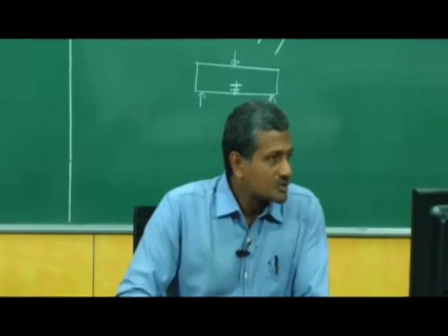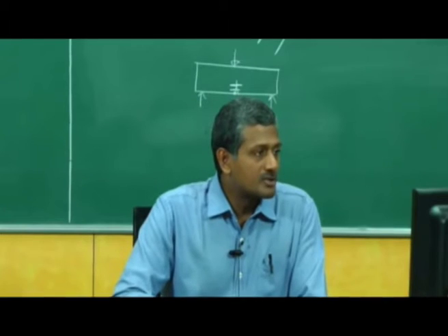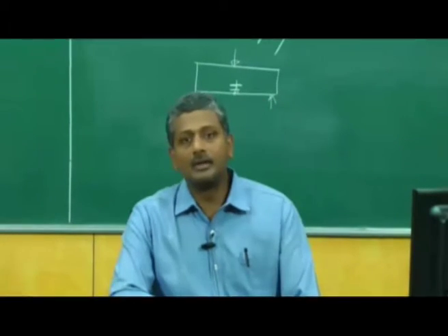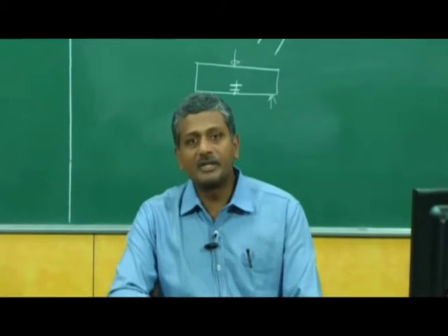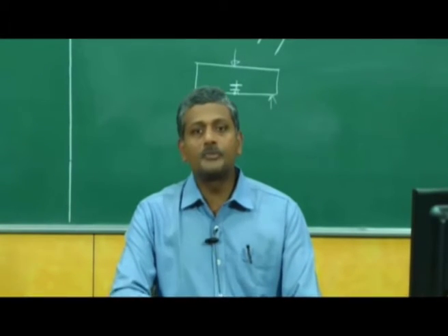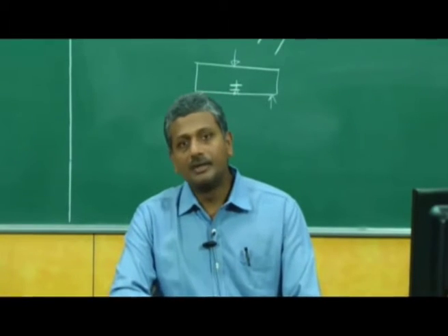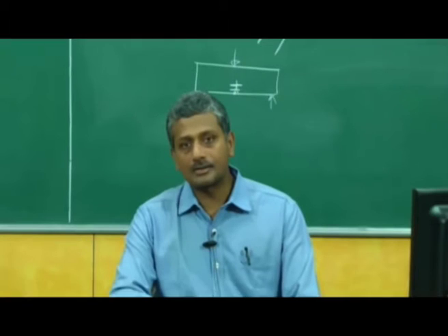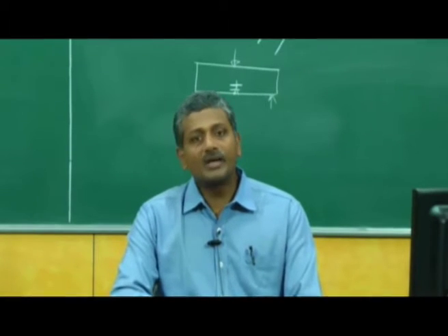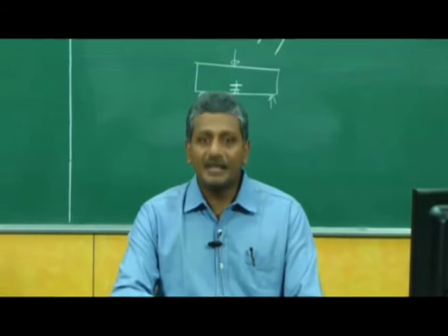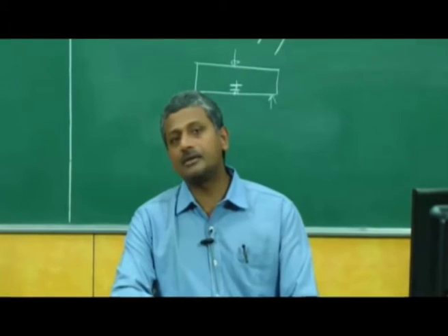Now, one more question is, when cylinder strength is more accurate than cube strength, why is cube strength referred to with regard to grade of concrete? Okay, now please remember that cubes are used in our country for determination of compressive strength of concrete. There are several countries that actually use cylinders. Okay. Now, why is the cube used? The cube is basically used because there is a much easier way of testing cubes than cylinders.